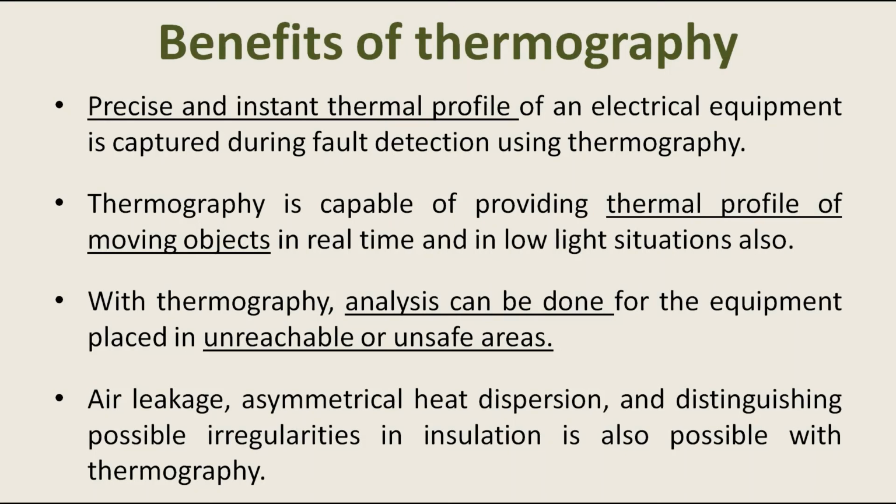With thermography, analysis can be done for equipment placed at unreachable or unsafe areas. Air leakage, asymmetrical heat dispersion, and distinguishing possible irregularities in insulation are also possible with thermography.